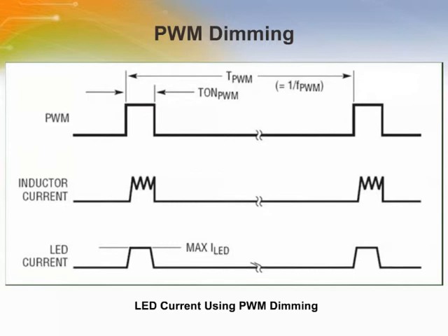When the PWM pin is low, switching is disabled and the error amplifier is turned off so that it does not drive the VC pin. Also, all internal nodes on the VC pin are disabled so that the state of the VC pin is maintained on the external compensation capacitor. This feature reduces transient recovery time. When the PWM input again transitions high, the peak switch current returns to the correct value.